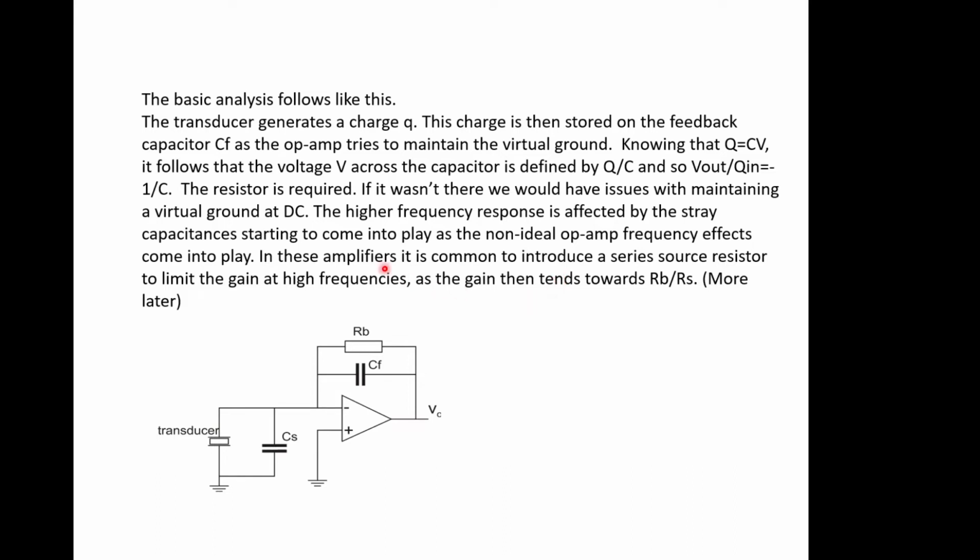To try and get rid of that, it's common to introduce a series source resistor to limit the gain at high frequencies. So that means we'll put a resistor here. And now we've got an RC time constant in this bit. We'll look at this a bit later in the course, so this is just an introduction to this. And then if you go to extremes, you could see that the gain will actually